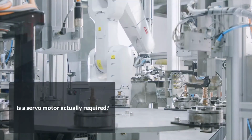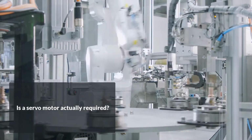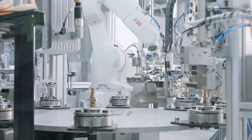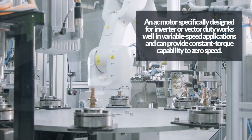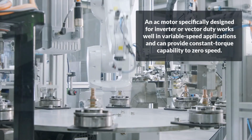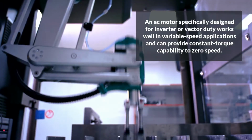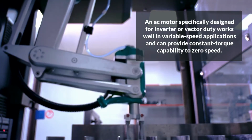An AC or DC motor with encoder feedback can also be used in many high-performance applications, providing good speed regulation and reasonable positioning capability. For example, an AC motor specifically designed for inverter or vector duty works well in variable speed applications and can provide constant torque capability to zero speed.